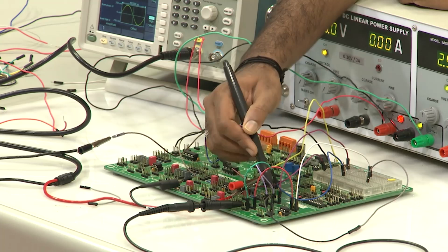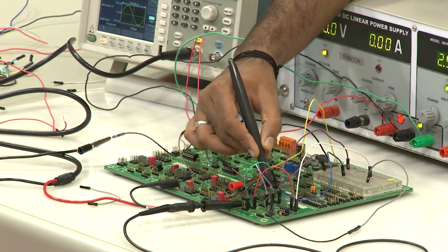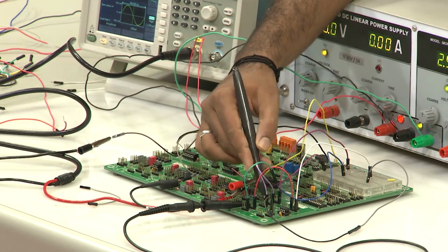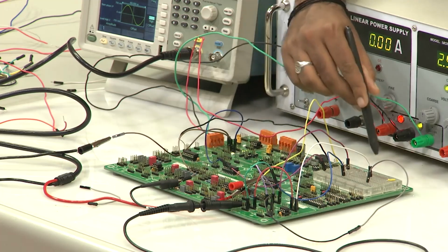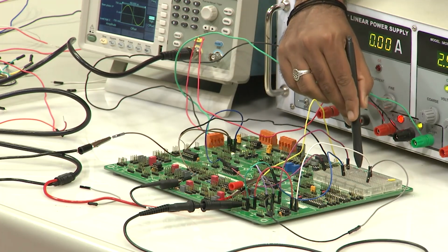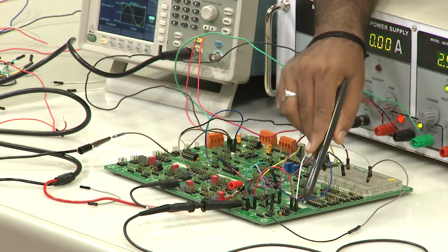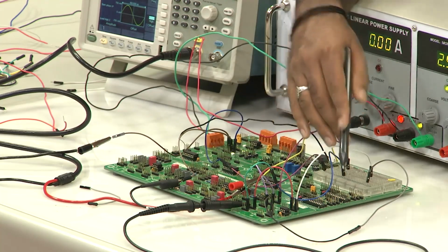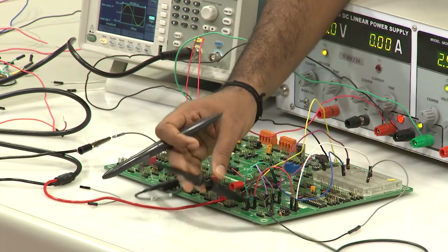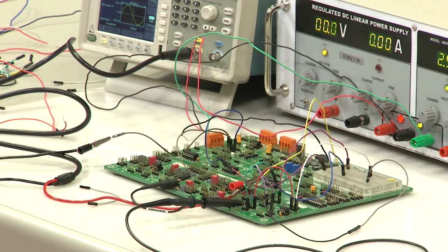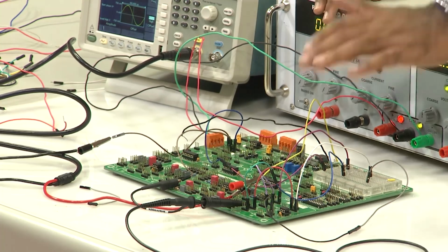The positive terminal of the op amp is grounded because it is an inverting op amp, and the output is connected across a resistor back to the input. We see the output from the output terminal using this probe. This is a very simple circuit, but the understanding that you get from this connection is very profound, which can help you in building more complicated analog circuits. So, this is how the circuit is connected.